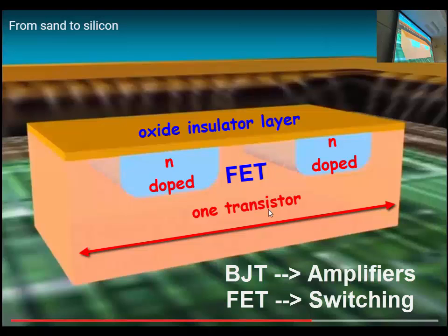If you're an analog person and you want to amplify a signal, junction types are very good. They're good for making an amplifier in your guitar amplifier or your stereo in your car, but they're not so good at switching. These things are great for switching ones and zeros. The reason is that this insulator has a super high insulating value. The resistance is enormous. You have to have a huge voltage to have any current flow through here. Silicon oxide is almost a perfect insulator.